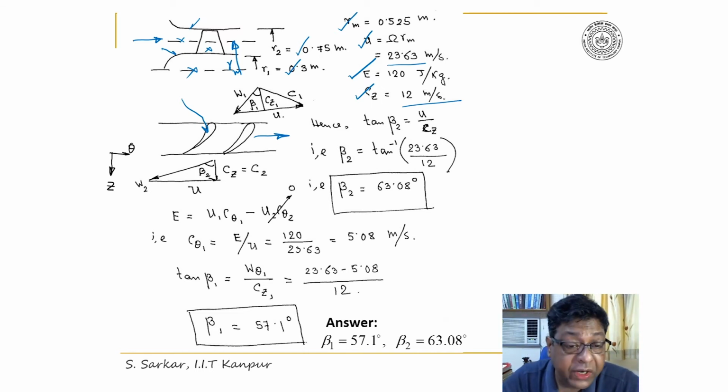Look here, the orientation would be different than that of the pump impeller. If you consider the direction of the rotation, U is the same. Now the pressure surface is the agency for the drive of the impeller.